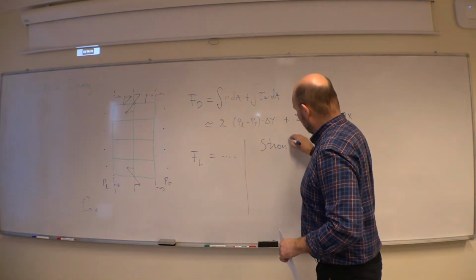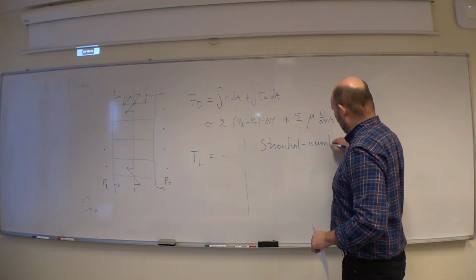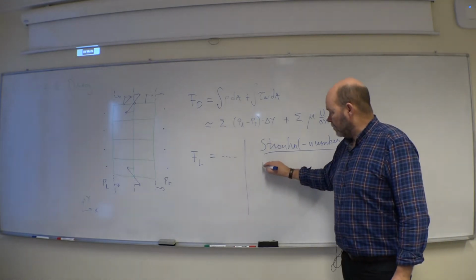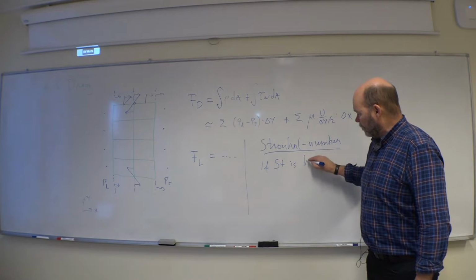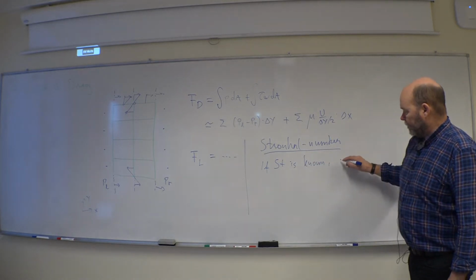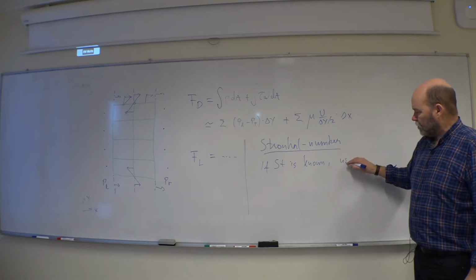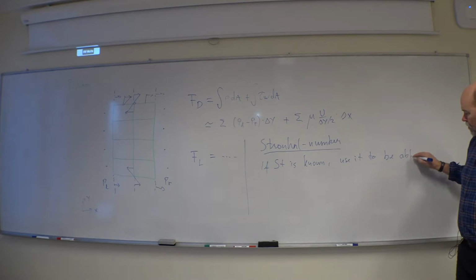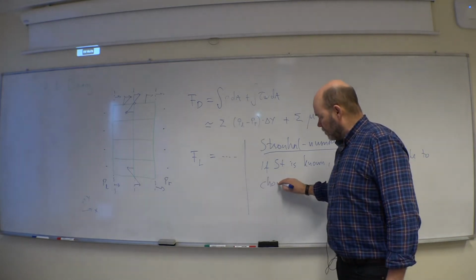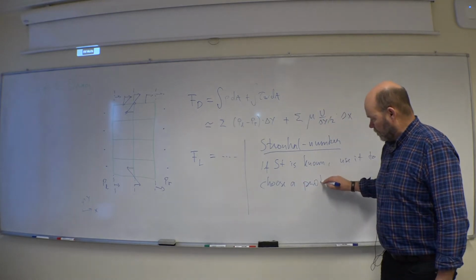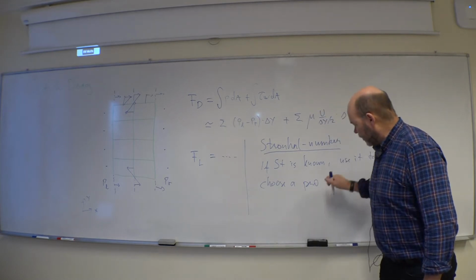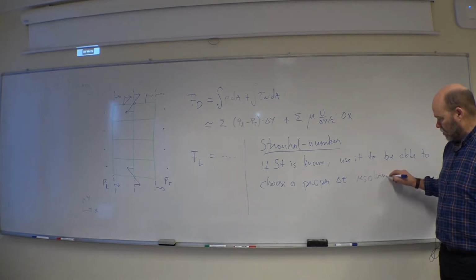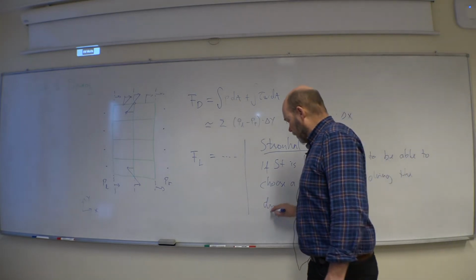Strouhal number: if it is known, it's only a time scale actually, but then you should use it to be able to choose a proper time step, resolving the dynamics in the problem.